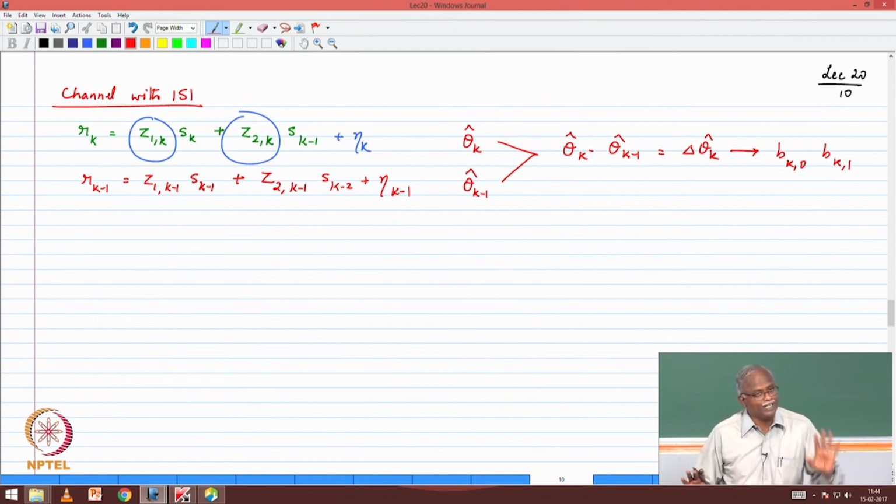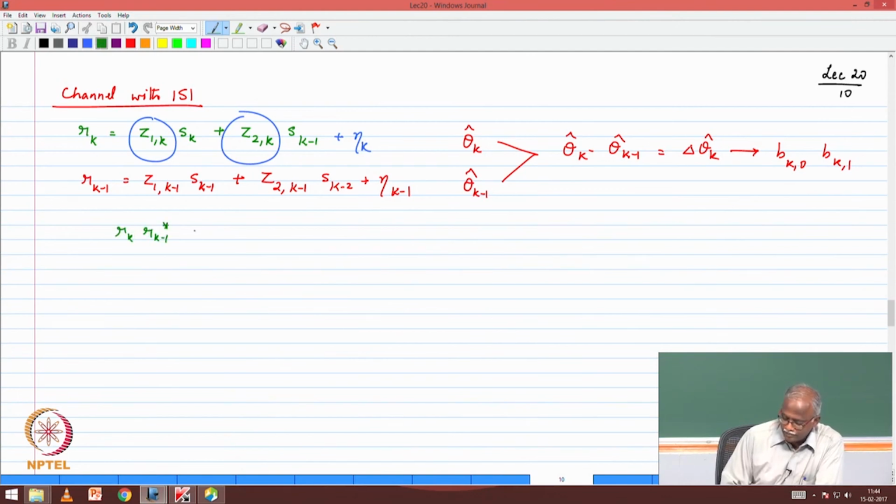Again, the same framework, differential encoding, and this is the received signal in the presence of ISI. Again, the right hand part of this equation is from the previous graph. Now, without any hesitation, if we go ahead and say, well, I know what differential detection is, it is Rk minus 1 conjugate. Please write down the expressions. You will find that there are lots of terms. There will be 6 terms. One of them is your desired symbol. That is basically mod z squared